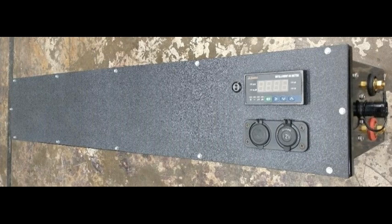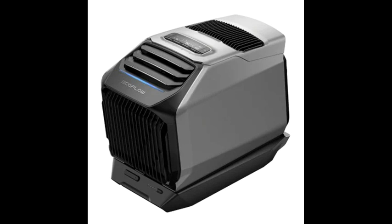The third is a custom-built battery pack consisting of 8 CALB 180 amp hour cells with a 4S 2P configuration, providing 12 volts and 360 amp hours. The last battery is from EcoFlow and mates to their Wave 2 air conditioning with heater. It has a 1,159 watt hour capacity and connects directly to the base of the Wave 2, so it doesn't power anything else in the trailer except the Wave 2.